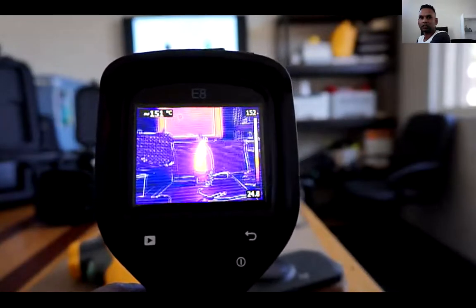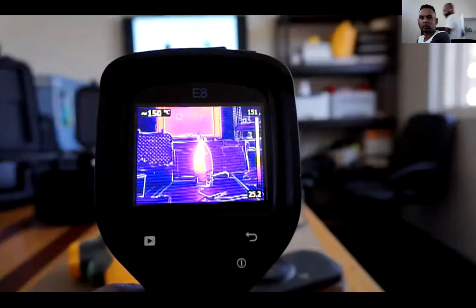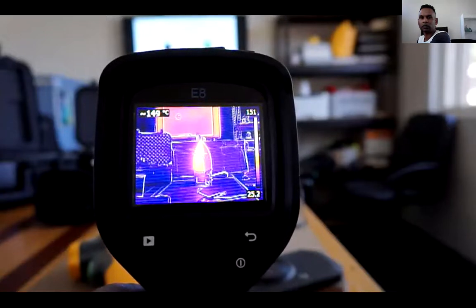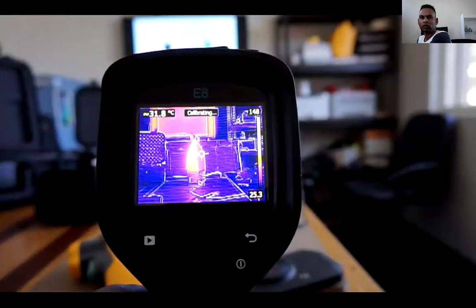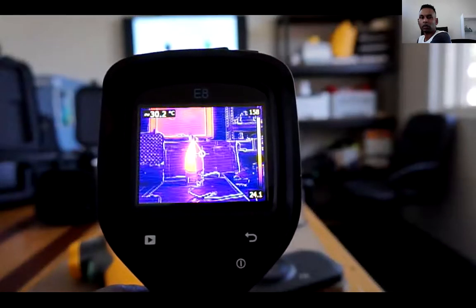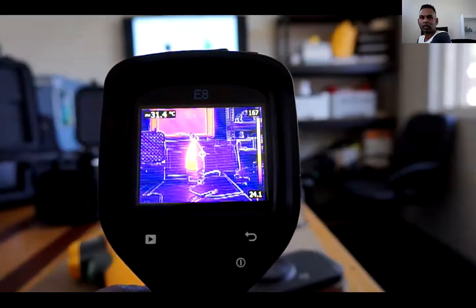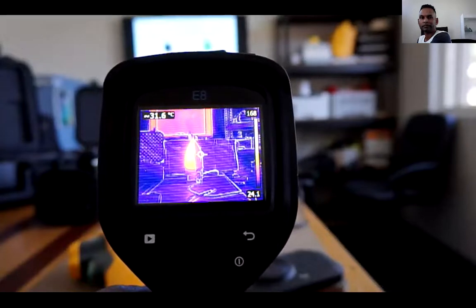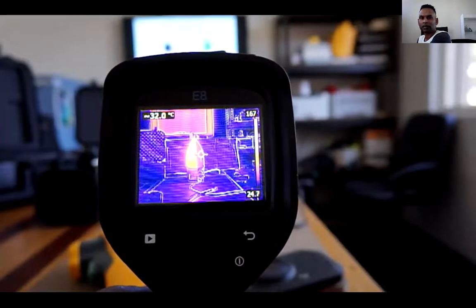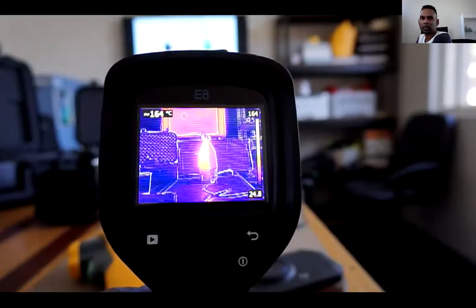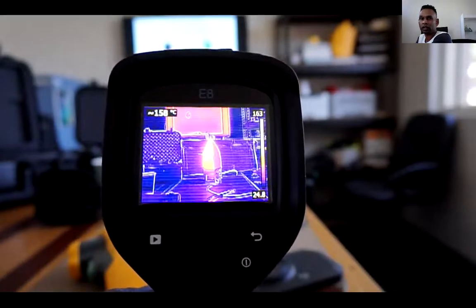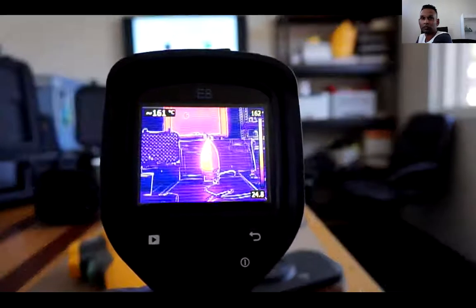We can see the left side, it's well above 150 degrees. Whereas the right side with the aluminium foil, it's only showing around 30 degrees. Okay, so the reason why, the left side, we're now working with a surface which has an emissivity close to 1.